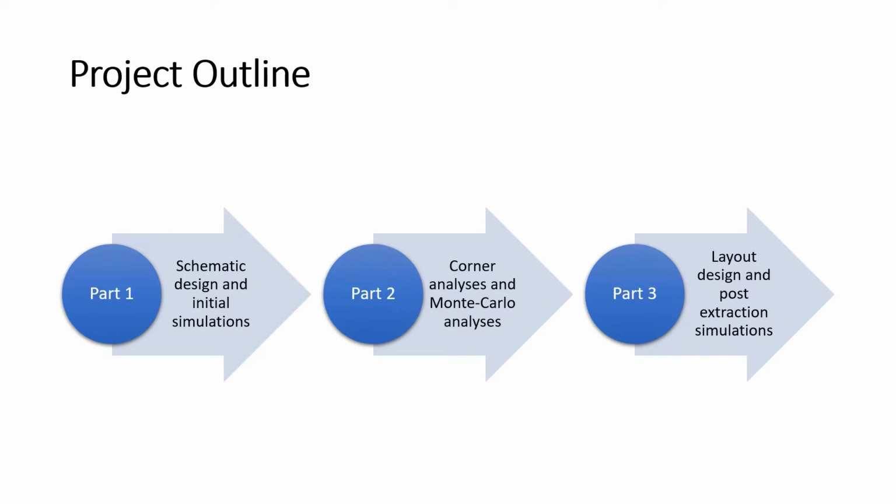The project can be divided into three parts. In the first part, I performed the initial schematic design and simulations, while in the second part, I performed the corner analysis and Monte Carlo analysis to test the design under different process corners and mismatch conditions. And in the final part, I performed the layout design and post-extraction simulations.